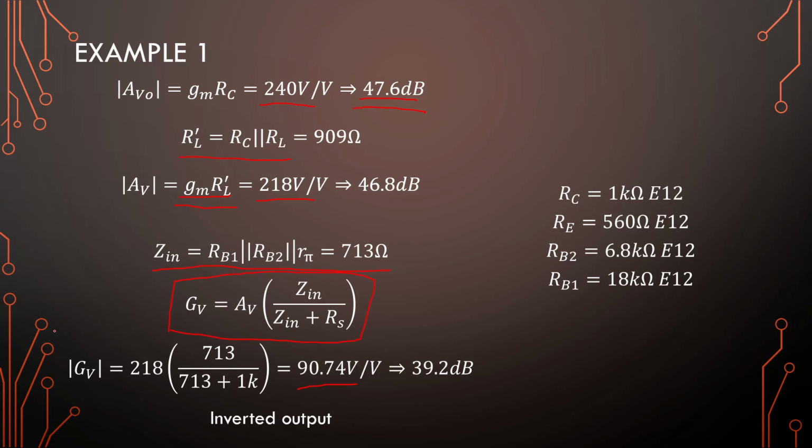Okay, because I work with absolute values here, it just makes the calculation of our decibels much easier. But you can see that this small impedance here with a large load on the input side, or a large RS, is not a good thing. Okay, but that is our amplifier designed.